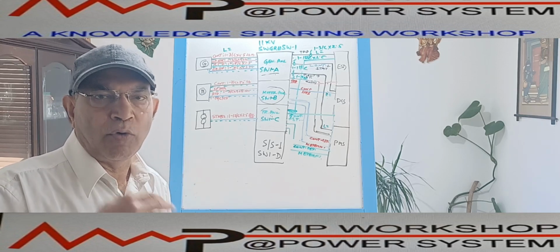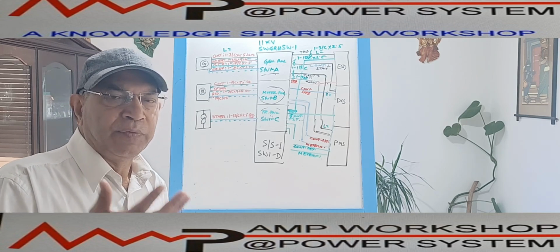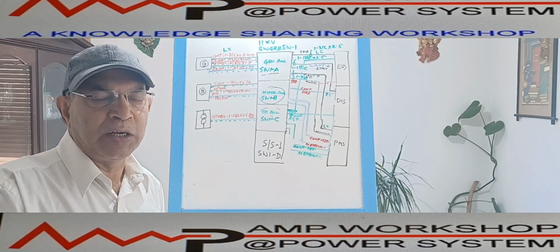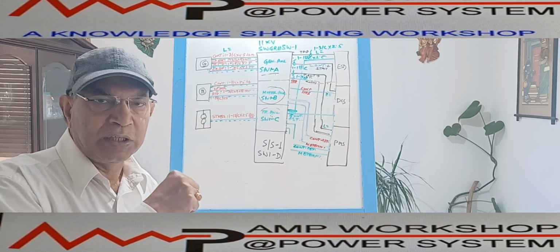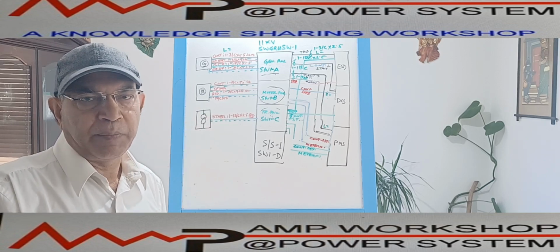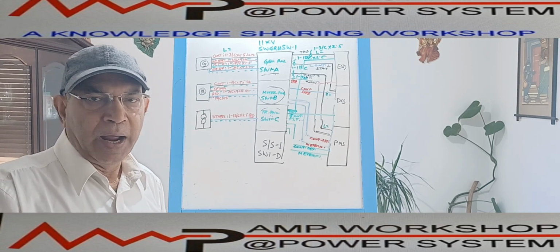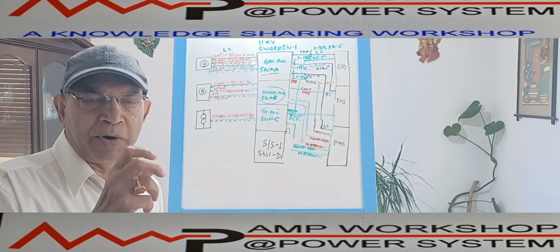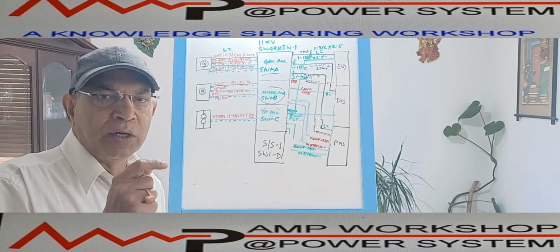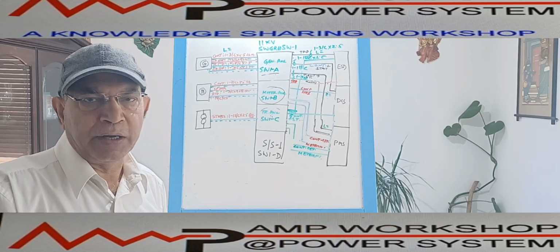In addition to this, if this 11 kV switchgear panel contains the generator control components like an automatic voltage regulator and your governor, in that case this generator switchgear panel also requires control cable coming from the skid for the controlling. There is a CT supply, current signal and voltage signal coming to the generator panel to connect with the AVR and the governor. And because the governor speed is controlled by the frequency, a PT voltage signal is coming. Along with this, a command from the governor is going to the fuel regulating valve.